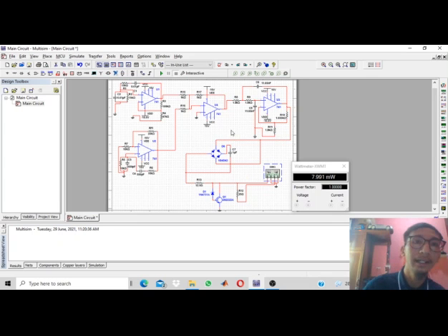Firstly, at oscillator 1 and oscillator 2, we get two outputs. At the summing voltage, it will change to one output. From the summing voltage, it goes to the low pass filter, which changes the signal to a low frequency, and from the low pass filter it goes to the rectifier. At the rectifier, the AC voltage is changed to DC voltage. Then we get the DC voltage and it goes to the basic shunt regulator circuit.